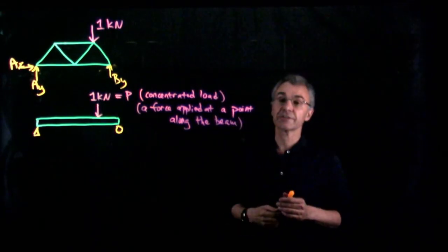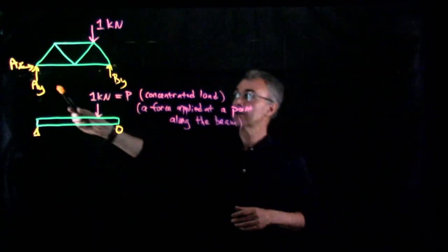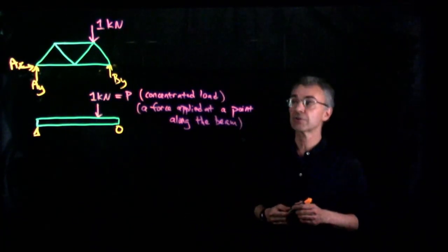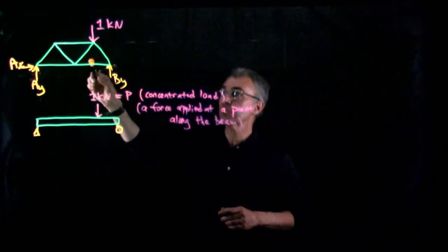So looking at the forces acting on the truss, we had the load forces, which the truss bears, its purpose for being there. We had the support forces, also known as reaction forces, which hold the truss in place, typically exerted by the ground below. And then we had the internal bar forces.